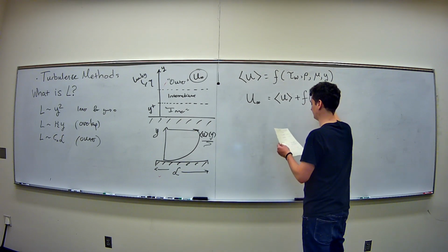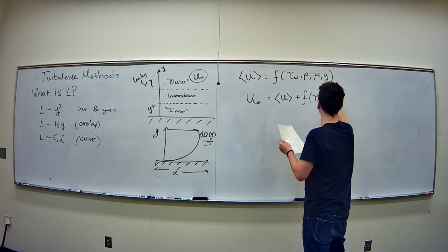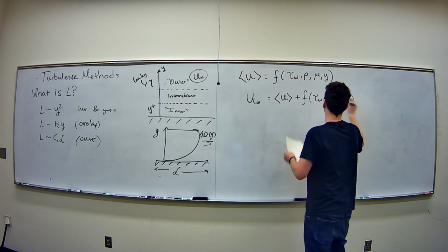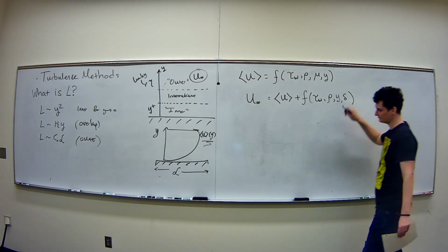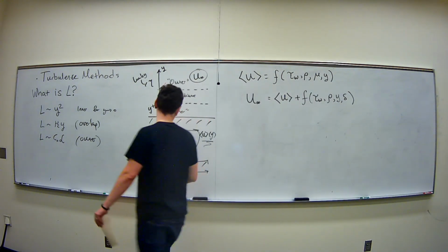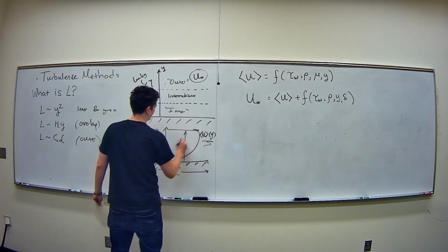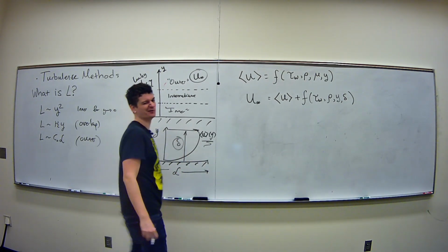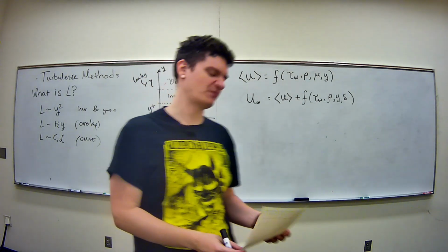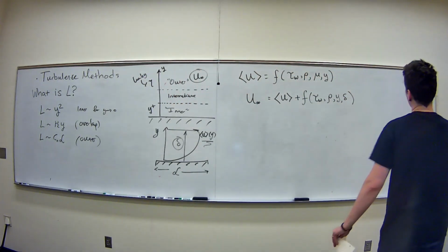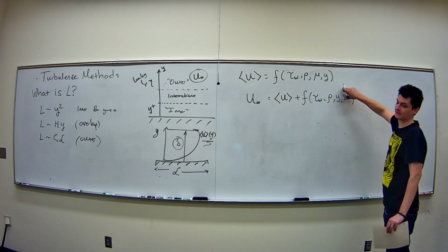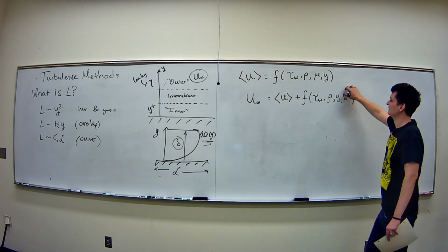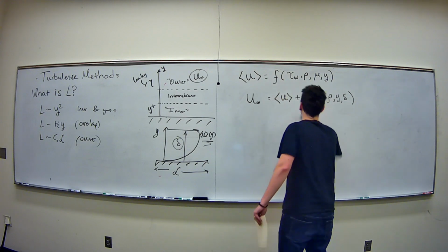Okay, let's see if you can hold with me on this. Rho and then y and delta. Okay, so I have a length scale here, delta. Delta being the turbulent scale away from the plate. So there's some length scale where that's going to be true. I won't go into how you actually pin that down. That is the theory of turbulent boundary layers, which can get you a handle on it. But then these functions make enough sense. This should not be f, this should be g.